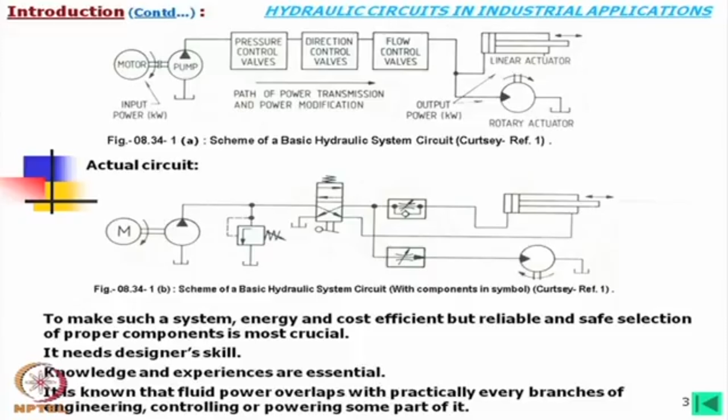Usually there will be a motor to drive a pump, and that power gives translatory motion as well as rotary motion with torque conversion. And this can be controlled also. For example, we are controlling the speed through a flow control valve, and in this case the control signals also pass through the oil hydraulics. The oil medium is very good for transmitting control signals.